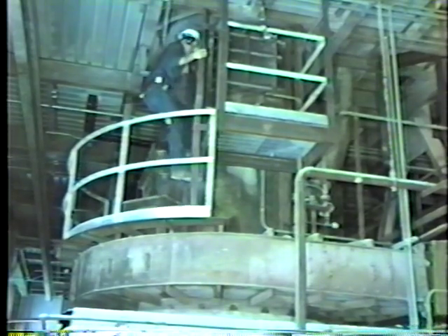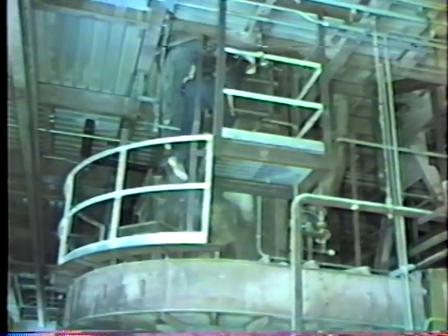This man has just climbed to the spinner separator level, where the coal is sized by spinning angle iron blades. This is an overview schematic of the Foster Wheeler boiler with the Williams pulverizers located at the ground floor, the burners located several stories higher, and the upper furnace section complete with superheater and convection section.